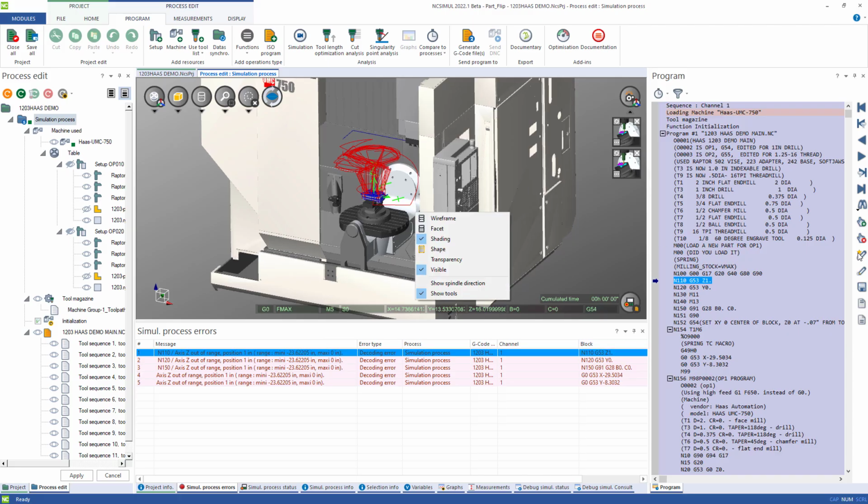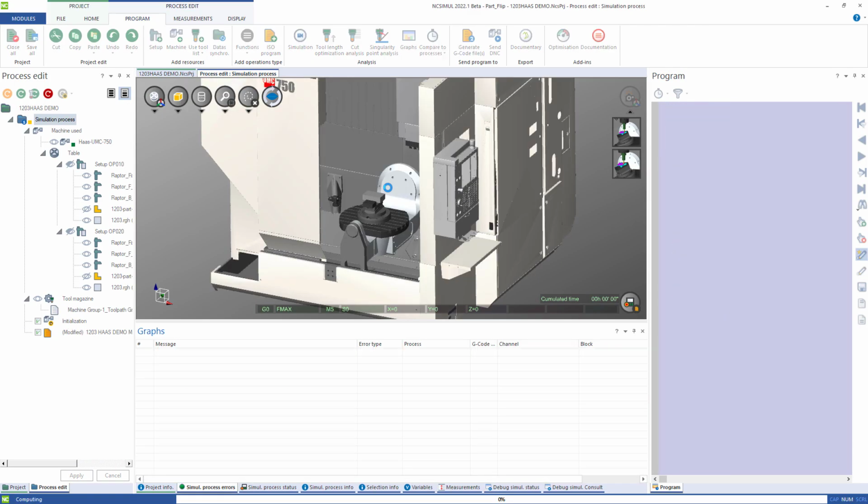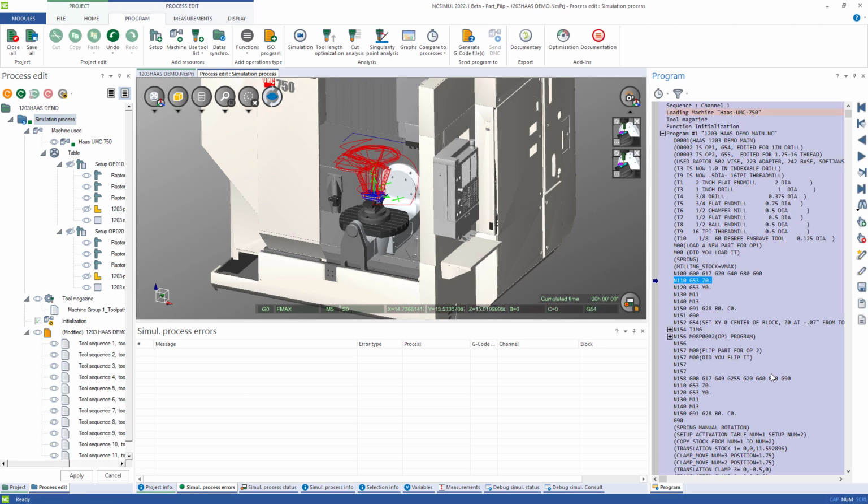So I can just go over here to the right-hand side, and if I click this icon, the pencil with the star, it's going to turn this into a quick edit mode. And then I can go right into the G-code, make my change directly from here, change my Z value by 1 inch or more, and it just happens to be 1 versus 0 anyway. And then when it does it, it reruns that syntax error check and makes sure that's a new good value.